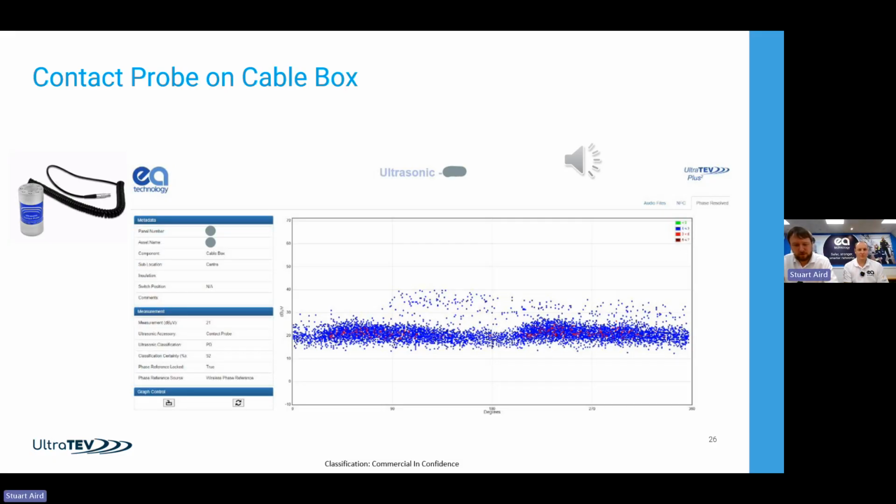So it's the first one of our demonstration, and it's the least clear you're going to hear today. The audio file for this isn't particularly clear, but there are signs in the phase plot that this looks like PD. There's this clustering going on, and there's our classification there. So, question to yourselves, with that information in front of you, would you be thinking of taking an outage? There's a quick poll, I believe, that's been pushed out on that.